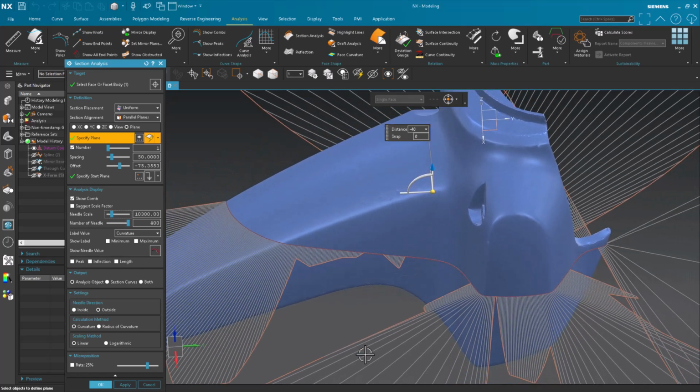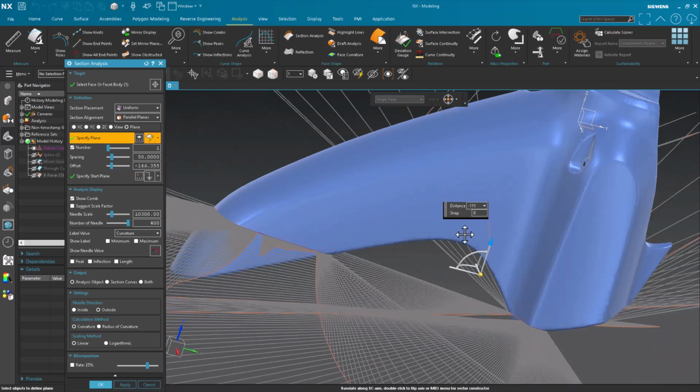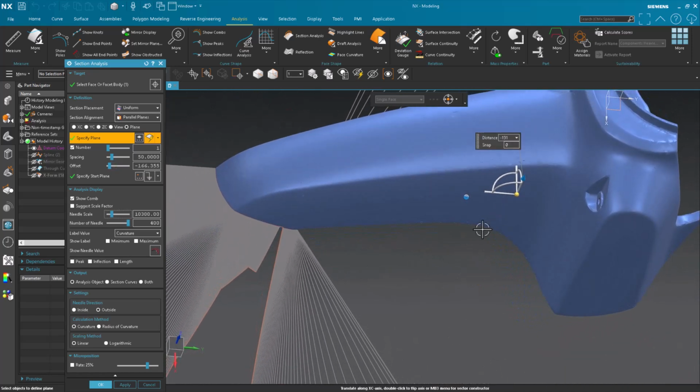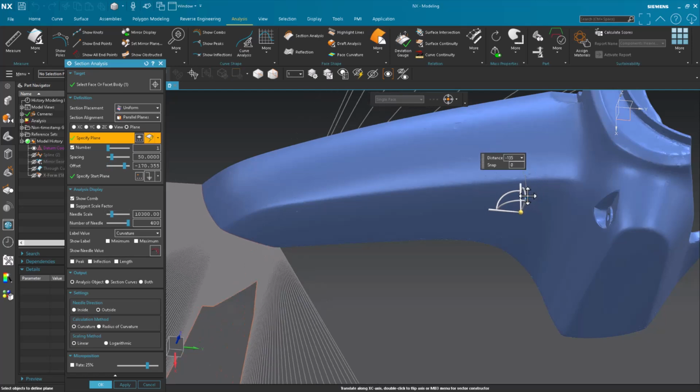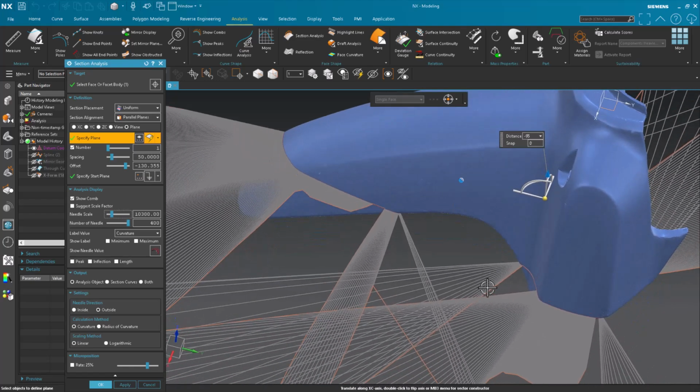So I'm going to make a judgment call that I need to deviate a little bit more over in this area in order to make that side surface smooth. Because once I make that surface, I'm going to get all these surfaces in there. I'm going to put in a blend. Well, that blend is going to be where that curvature changes, right, at that tangency. Okay, and I could do the same thing for the forward end. Just taking a look over here and sort of get an idea of what's going on. Okay, nothing too crazy, pretty much what I expected.